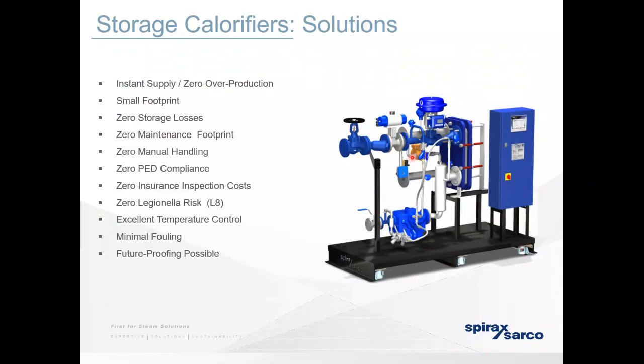So a solution: how can we reduce all that footprint? One way would be to use a heat exchanger package. It means you can almost instantaneously heat water, so there's no need to store it. It has a smaller footprint, so the area in your factories can be better utilized. It doesn't have any storage loss because there's no storage, so you're not losing any radiant heat from a large volume of water. No manual handling, which is more to do with the replacement of equipment, because it's a package unit.